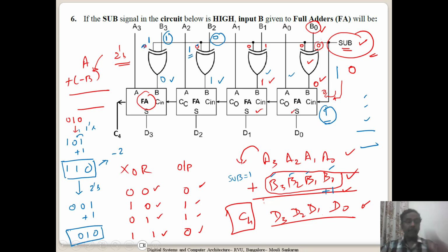So remember, if I am considering only a 3-bit value, and the MSB is set, then it is a negative number. If I want to know the magnitude of that value, I do the 2's complement and get the magnitude. And originally, if I am starting with some number which needs to be represented in negative form, I do the 2's complement and get the value. Whenever I perform a 2's complement, I will get the MSB set to indicate that it is the 2's complement representation of what I originally started with, and that gives me a clue that it's a negative number.